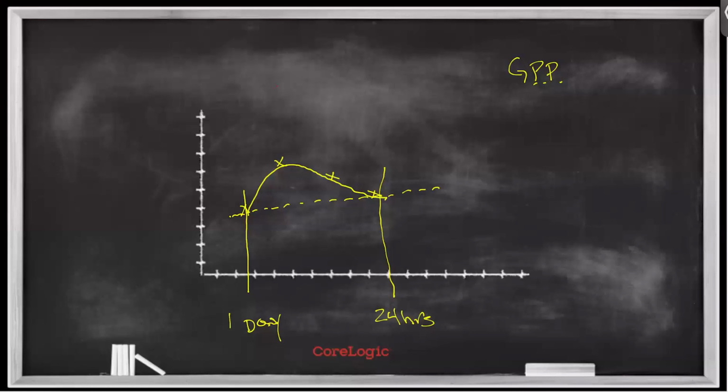If I took those two readings 24 hours apart, then this would indicate to me that I do not have humidity control. And the reason for that is that, in that first hour to 2 hours of the drying process, that's usually where this spike is going to occur, right in this 2 hour range approximately. And that's where I begin to establish my humidity control, somewhere on the back end of that initial visit. So one of the first things that I want to encourage as a best practice is that when you're trying to understand whether or not you have established an appropriate humidity control, you need to take more than one atmospheric measurement on that initial visit, right?